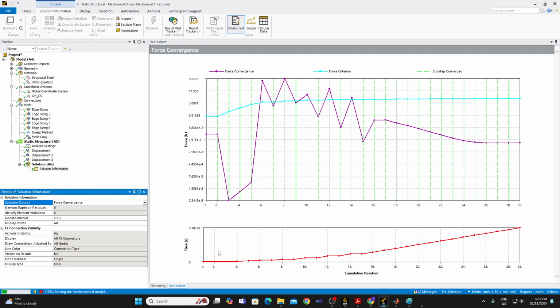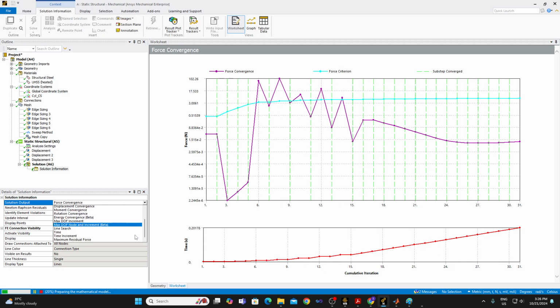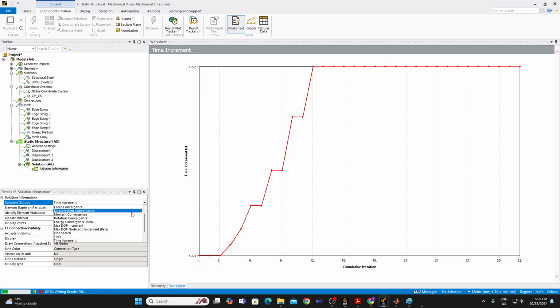Now we have already converged about 80% of the solution. So as I said, this time is only an indication of the load level, or how much the solution has converged. So it has converged only about 20%. And it will take time because it is taking an increment of 1 in 100 second. So it will probably take 5-10 minutes to solve.